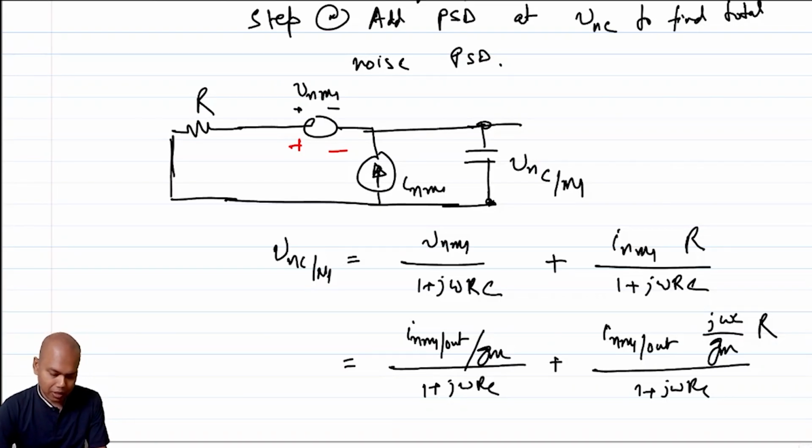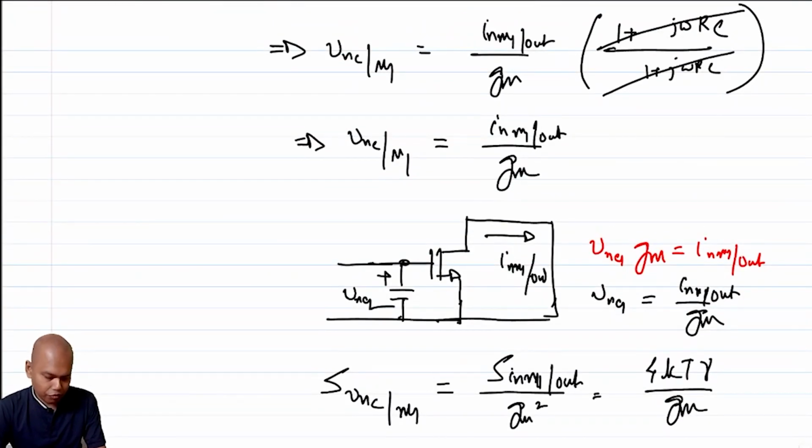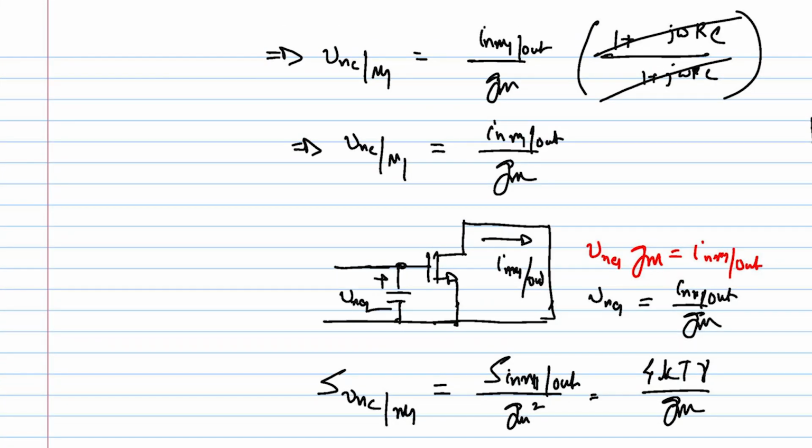The other part that is important to understand is that what we just did was find the equivalent noise voltage at the input of this transistor, across the capacitor. But that does not mean you can replace this capacitor with a voltage source, because if you do that, you will not be able to take into account the effect of the other noise sources that precede this contraption. Okay, so let's complete this thought. Let's complete this noise analysis.